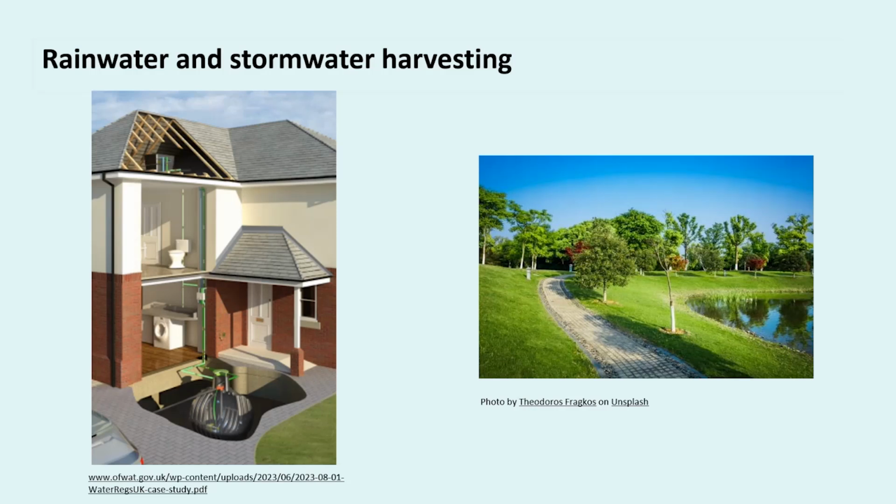In such cases, a centralized rainwater harvesting system could be used to capture rainwater from all roofs in a development, including commercial buildings for mixed-use developments, and convey it to a large underground storage tank or series of tanks. The storage volume, if you were to take this approach in Sussex North, would require storage of 35 days of supply to cover dry periods. And the rainwater would be treated through a centralized treatment plant prior to being pumped back into the individual homes. This is the approach that we're adopting in Sussex North.